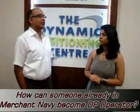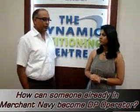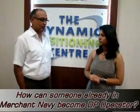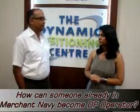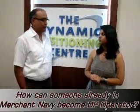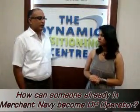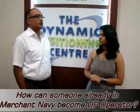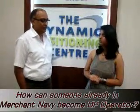So how can someone already in the merchant navy become a DP operator? When a marine deck officer has decided to become a DP operator, he has to go through a training scheme which has been laid down by the Nautical Institute in London. This training scheme has 2 shore-based courses and 7 months of on-board training. Shore-based courses include a basic course, which is also called the DP induction course, and an advanced course, which is also called the DP simulator course. And the on-board training includes a 30-day DP familiarization and 6 months of DP watchkeeping experience.